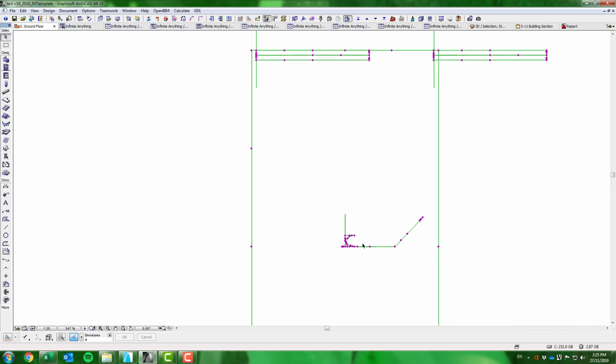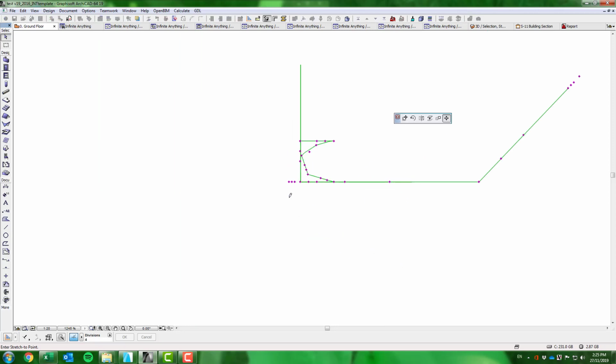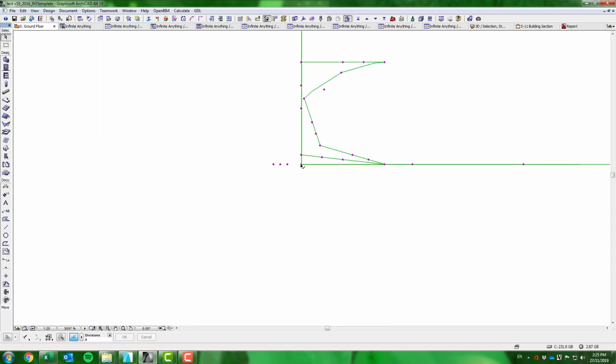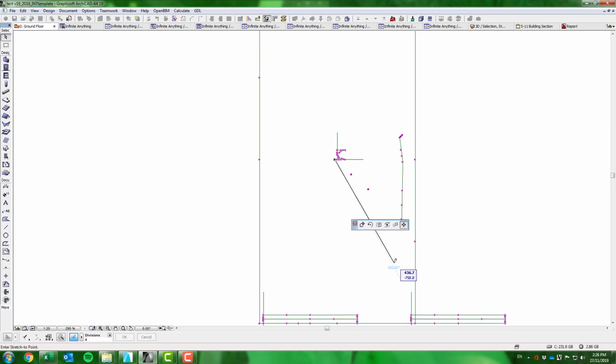And then I do my path. And I just move the path. Oops, that's the wrong node. That's part of the profile node. So I'll just move that out of the way. Grab my path node. Put that back in. Now you have to work out basically which way this tube is wanting to run, because it'll invert itself if you run it down the wrong direction. So I'm just going to bring it outside. Whoops, don't want to put a curve on it just yet. You can curve the path, obviously. I just want to see what's going on first.